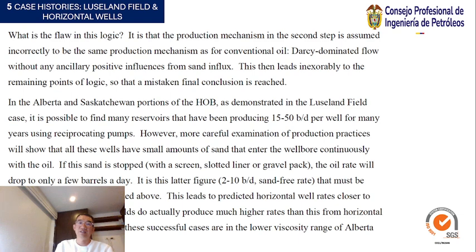It is that the production mechanism in the second step is assumed incorrectly to be the same production mechanism as for conventional oil: Darcy-dominated flow without any ancillary positive influence from sand influx.